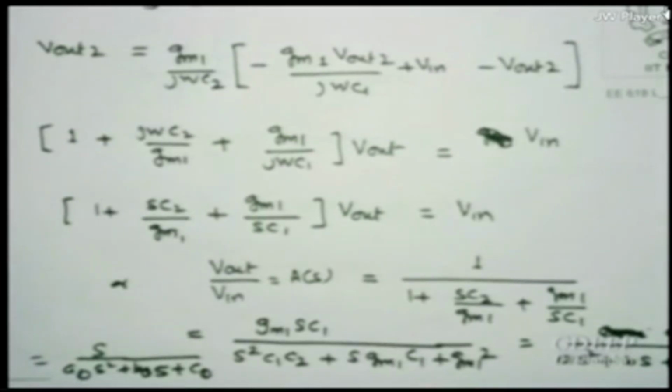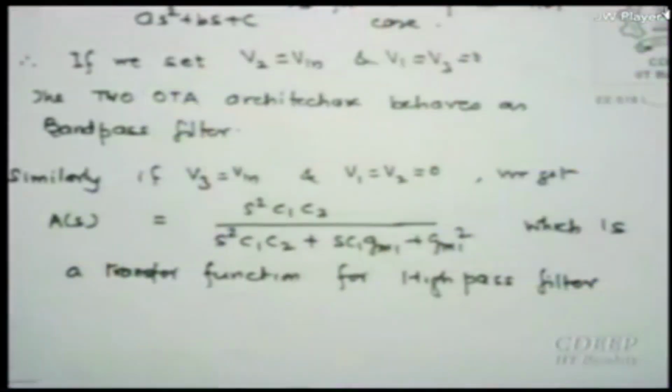Oh sorry, this is S, it is a band pass. If what would have been high pass? S square, yeah, sorry, it is band pass. So let's see, the two frequencies are omega 1, omega 2, essentially the band in which the output is 1, transduction has the magnitude of 1. So this is a band pass filter, as I say, you are right.